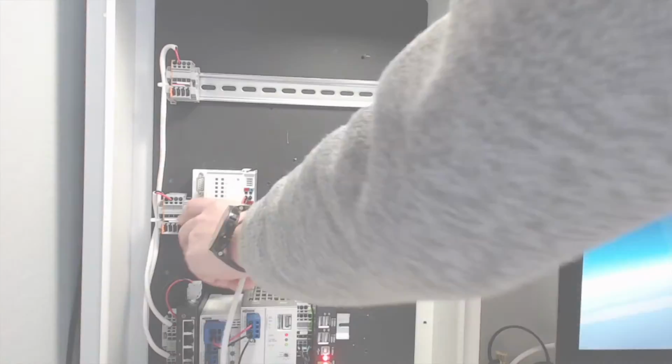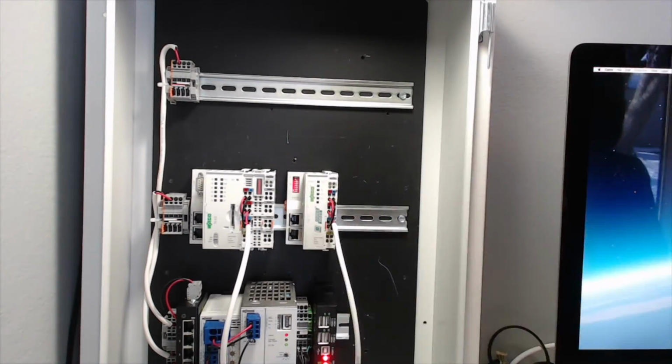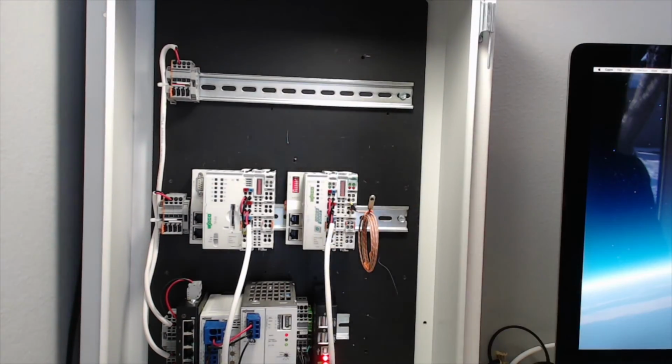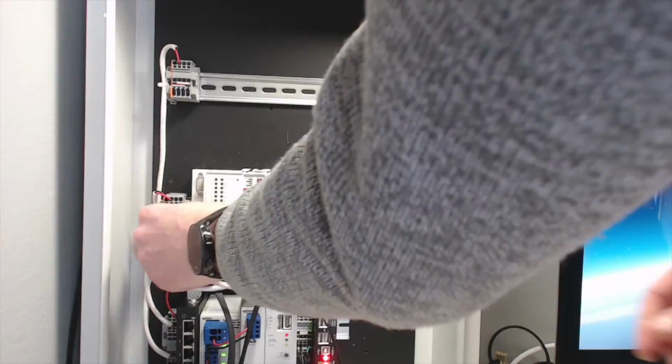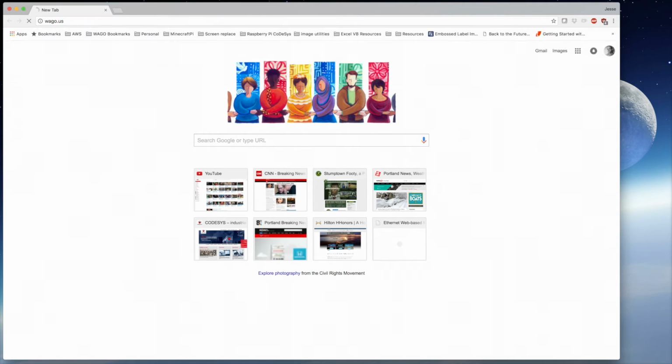get it set up. I'm using 16-channel digital output on the PLC and 16-channel digital out and 2-channel thermocouple input for the ProfiNET coupler. I'm wiring the coupler to port X2 of the PLC.